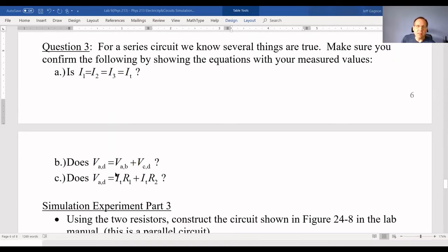And then this is almost the same question here. Another way of writing the voltage drop across AB is using Ohm's law. We can rearrange it and say that delta V, the voltage drop, is the current times the resistance. So if I take my I total and multiply by R1, because remember, the current's the same throughout the entire circuit, this is the current that goes through R1 times R1.